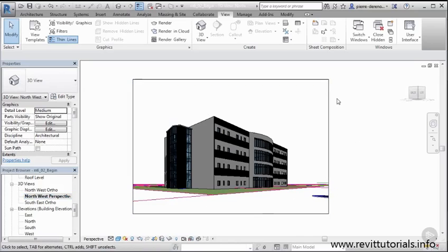Create a nice 3D view, and you can see the view you get here is pretty dramatic. We get a nice perspective here. Nothing is exactly parallel. It's not how our eye sees it. So it's a really nice way to get a camera set up. And that's basically how you access your camera. You place it into your project, and you rename that view. So in the next video, we're going to talk about working with some site elements and making some additional adjustments to this view so that we can get the desired scene that we want.